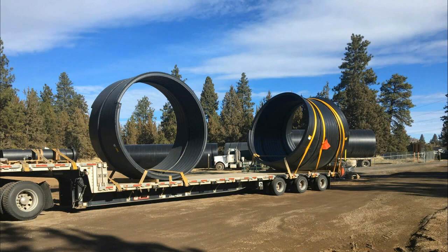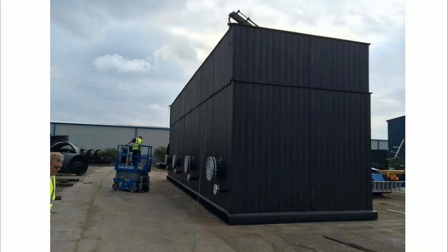As we said earlier, we can accommodate directional changes, horizontal, vertical bends, manhole structures, but this slide reinforces the fact that we can do that in diameters up to 132 inches, and this shows some fabricated bends using 132-inch Weholite to eliminate manhole risers and junction structures and directional changes. It's just an advantage of Weholite.